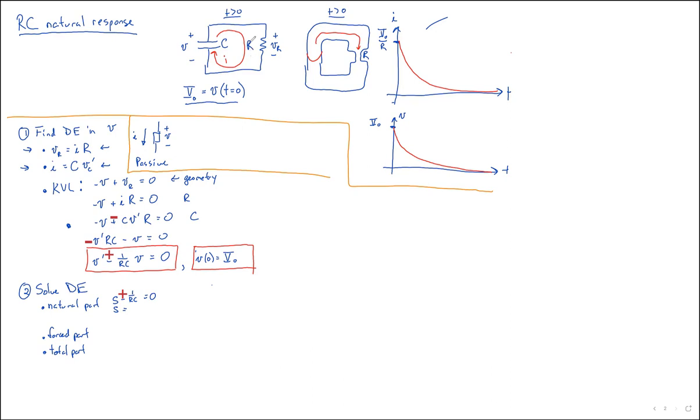So I did not do that up here. Here, R and I works, but take a look at this I direction versus the voltage across the capacitor. Here we've defined it the opposite way, that the voltage is more negative entering and more positive exiting. So if that's the case, I have to flip the sign.